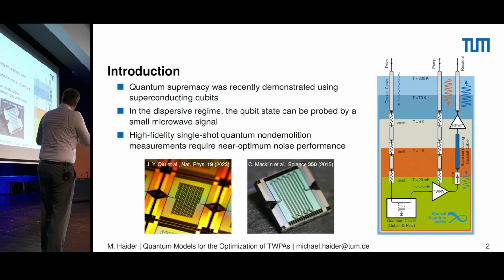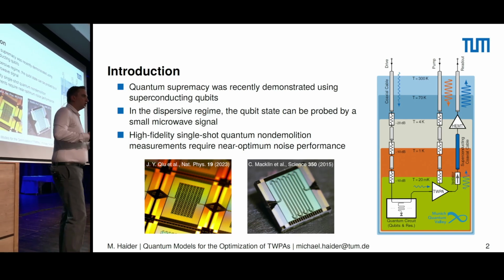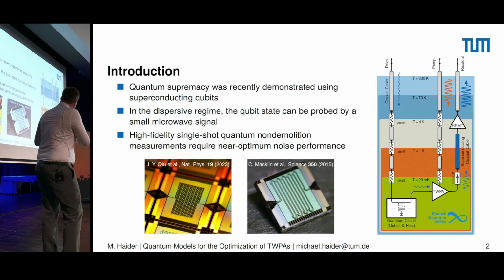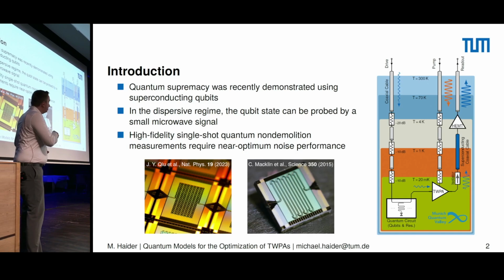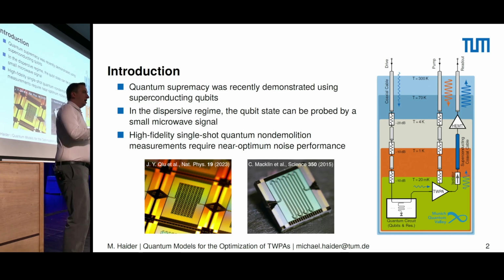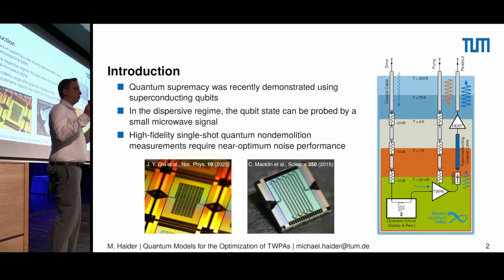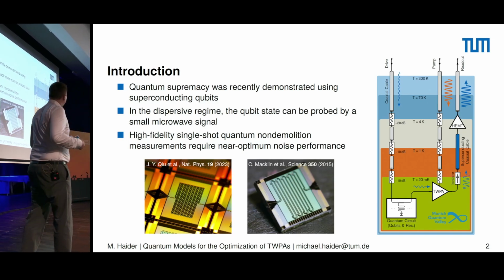What you get is a dispersive shift for the pulse that propagates along here. Here we are talking about signal levels in the range of tens of microwave photons, so ultra low power signal, not to interfere with the state of the qubit. Now you want to classically detect that signal at room temperature and discriminate whether you have a qubit 0 state or a qubit 1 state. So you want to do the readout, and of course you need to amplify.